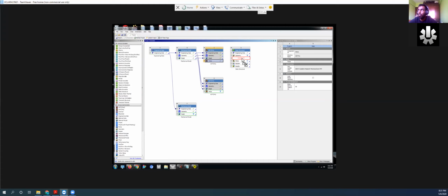And drag it over to the model. So the model of the static structural box that I just put in, okay? And then it's going to ask you: transfer solid composite data, transfer shell composite data. So I'm going to select transfer shell composite data, okay?